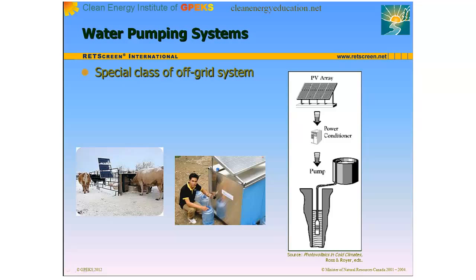The power conditioner is an important part of many pumping systems. Depending on whether a DC or AC motor is used in the pump, the conditioner may be a DC-DC converter or an inverter. The power conditioner helps the photovoltaic array provide the high current that may be needed to start the pump, even under low sunlight conditions, and operates the array at a voltage that generates maximum power, regardless of the operating voltage of the pump motor. A battery can fix the voltage and provide starting current, thereby replacing a DC-DC converter, but this introduces complexity, maintenance, and inefficiency.